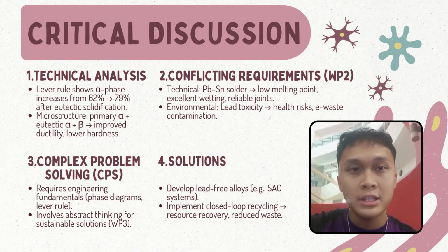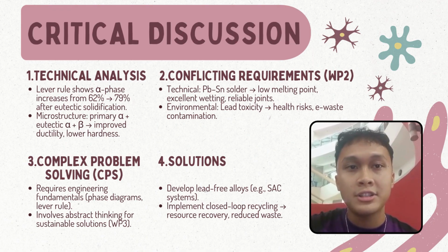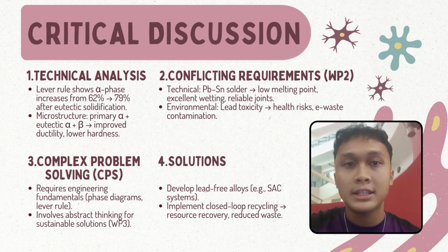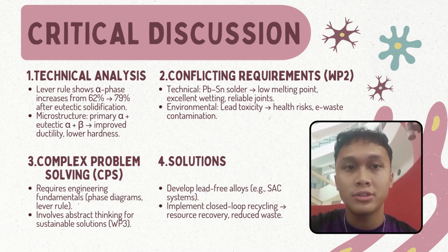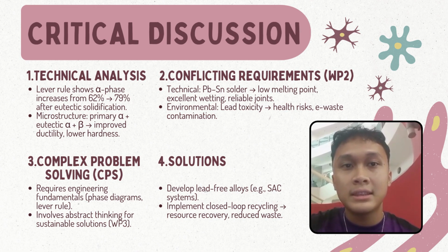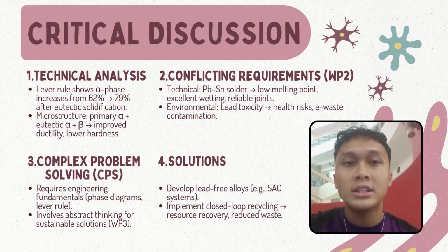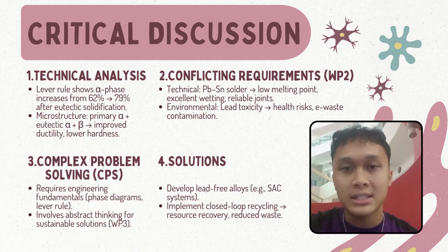In conclusion, the lead-tin binary system is a simple eutectic system widely used in soldering. The eutectic point is at 61.9 weight percent Sn at 183 degrees Celsius.